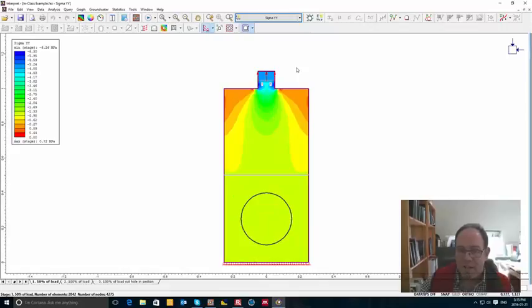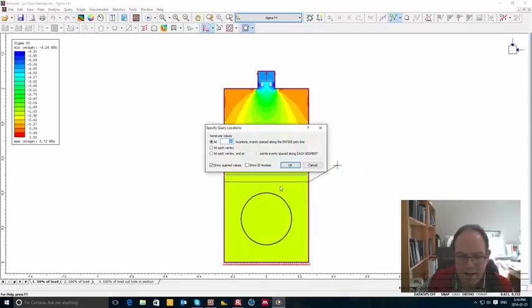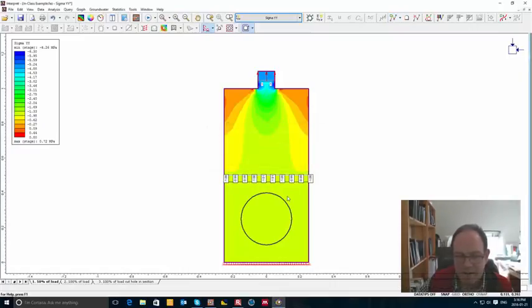So one very nice capability of the Interpret viewer is that you can plot some of the data. So we'll add a material query here, say right around here, which lets you draw a line, okay, and then push done, and say we want to know the data. We want the data printed at 10 different evenly spaced locations on that line.